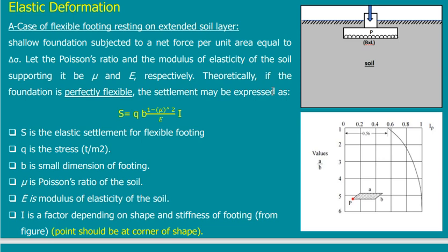We said before that in many cases, if I have a footing like this, I can just assume that the compressible part beneath the footing will be twice the B. If this is B by L, then I can take this B, go down to twice the B, and consider that whatever is beneath will not be affected. This is one approach, and it is possible to use it.